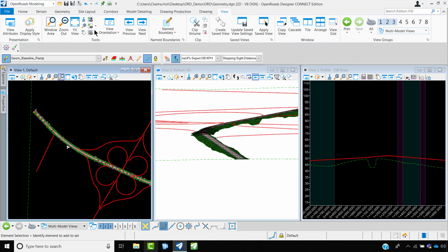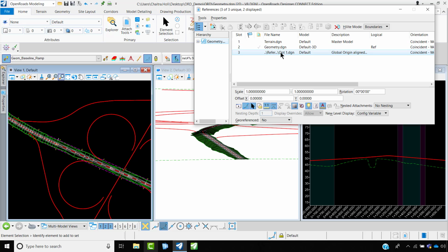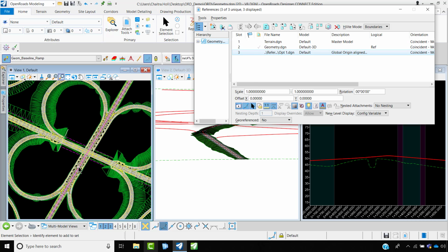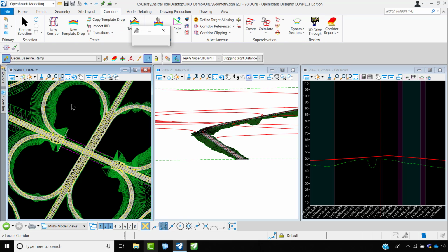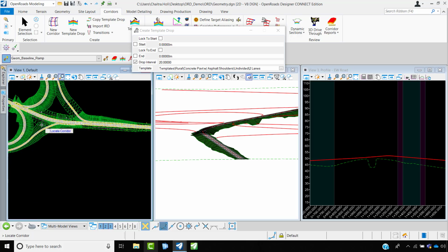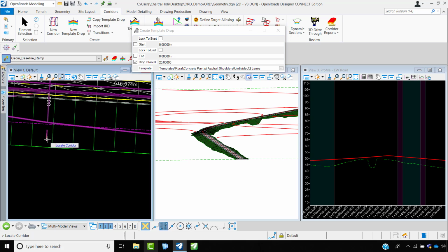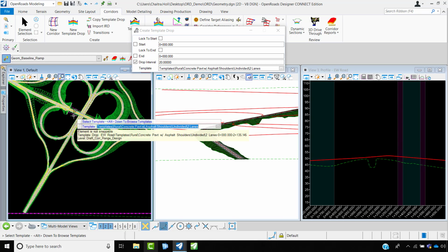Okay, let's go ahead and add the bridge template too. Let me switch it on, the extent where I want to add the bridge portion. In a similar manner, go under this corridor. Now add a new template. Whatever you see in these yellow handles is created as your corridor. For this corridor, I want to add one more template, and alt down.